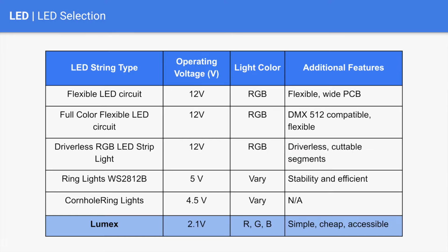For the LED research, we wanted to recreate an effect similar to that of the Alexa LED ring. However, most of the components we encountered required too much power to operate and were too expensive to keep our device in budget. Since it is supposed to be produced in mass quantities, we ended up settling on the RGB LED because of its low operating voltage, low cost, and accessibility.